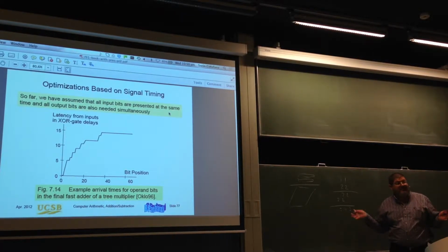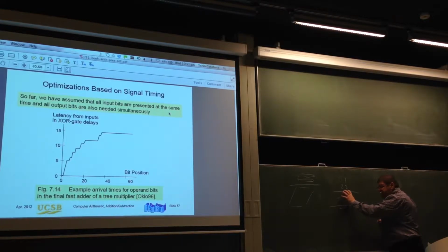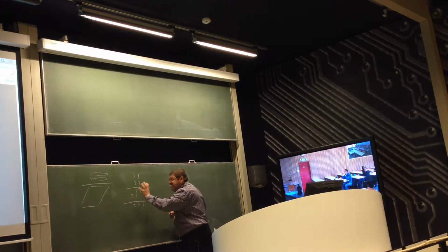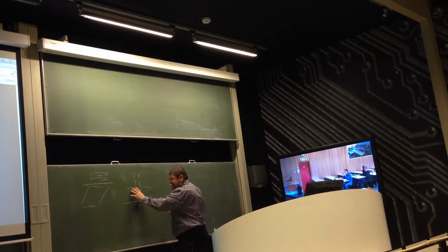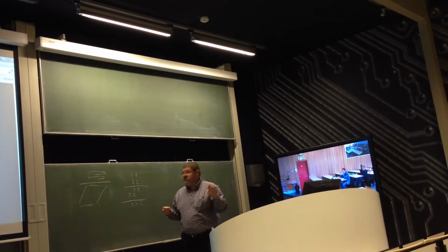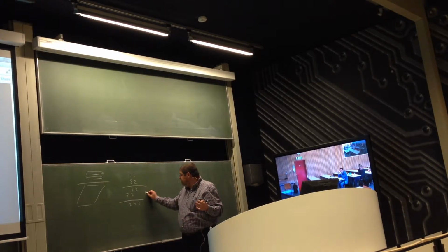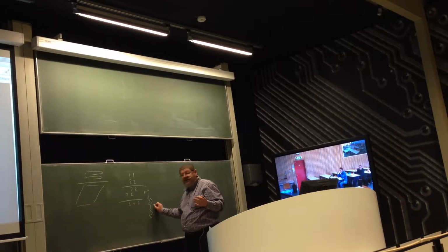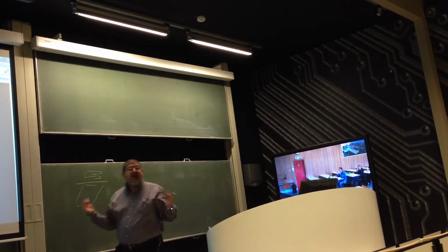Okay, there is no carry now, but I'm happy because my number is nice. Now, if you look at what will come out of this addition, you see that the least significant part is coming early, and the most significant part is coming a bit later in this reduction. We'll discuss how to do that reduction in just a second, maybe a couple of minutes. But essentially, in a multiplier, you have the partial product matrix, and then you reduce that to 2 rows, and then from 2 you reduce it to 1 row with an adder. Then this is a normal adder.